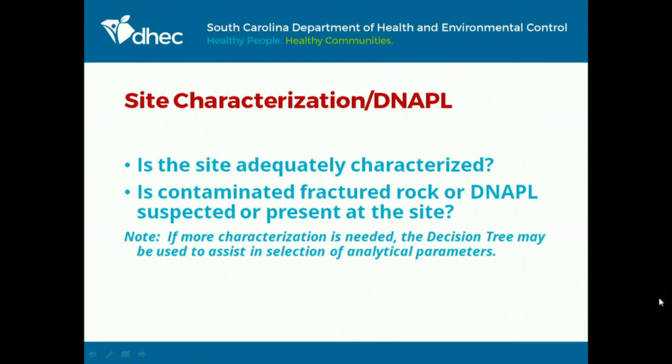If you have DNAPL or fractured rock, then you really need professional judgment to make good decisions. And the decision tree is really for unconsolidated materials without DNAPL. I think some of these technologies apply to DNAPL. You just have to be very careful how they're implemented.